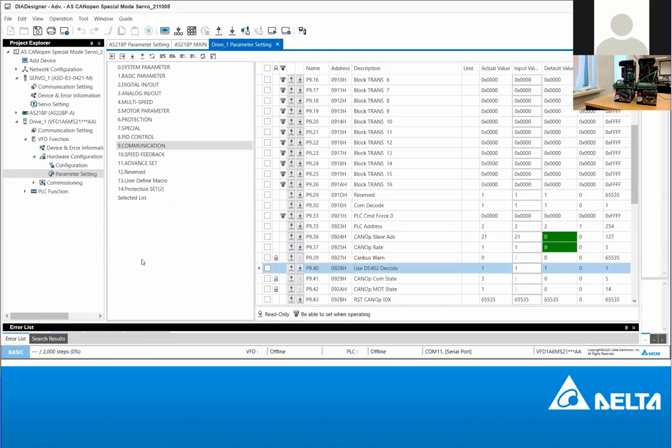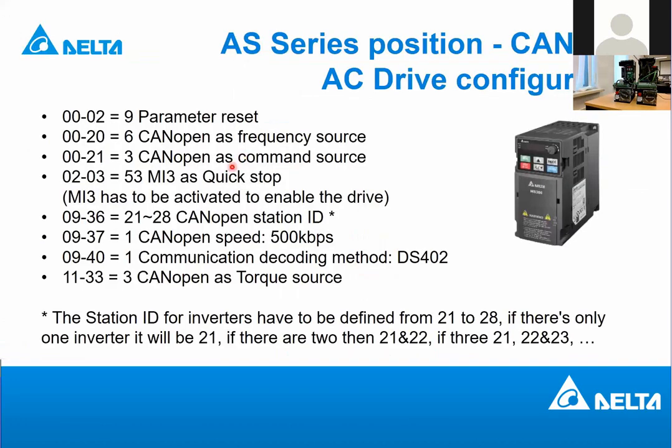And then what other parameter do we need to set? Yes, parameter 1133, CANopen toggle mode. So if the drive supports toggle mode, if you set this parameter, then you can make the drive operate in toggle mode. So let's just do it. We are not going to test this for this training. We are going to test the rest of the possible motions that you can realize with this CANopen special mode function, but we are not going to test toggle. Let's set parameter 1133 to 3.